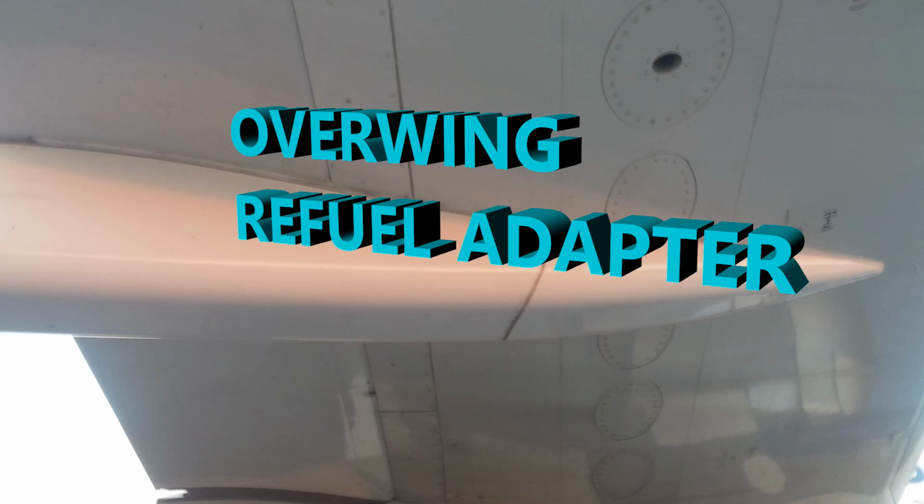You've got an adapter nut with the locking plate that holds that adapter in that spot, and you've got 2 O-ring seals that seal the joint between the adapter and the wing upper skin, to protect that. The lanyard attaches the refuel cap to the locking plate. You've also got a pressure relief valve, so you have that as well.